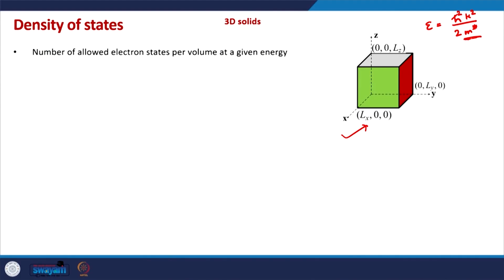But instead of the regular mass of electron, we need to take the effective mass of electrons. So, the EK plot will look like E equals h bar square k square divided by 2 m star. And now, with this notion of effective mass, we can ignore all the crystalline potential and the quantum mechanical nature of the electrons. Or in other words, the effect of crystalline potential and the quantum mechanical nature of electrons is now encapsulated in the idea of the effective mass. Okay.